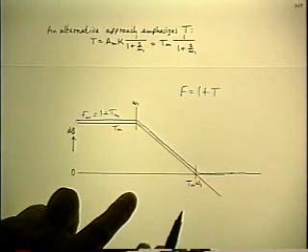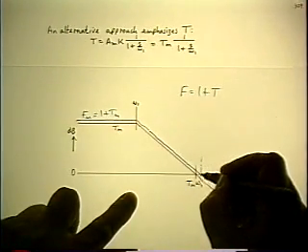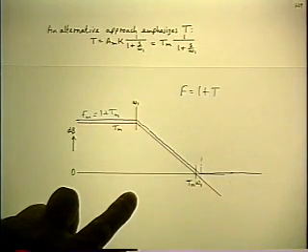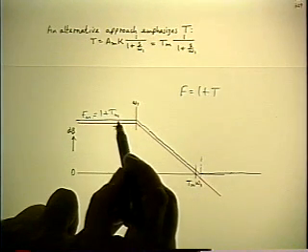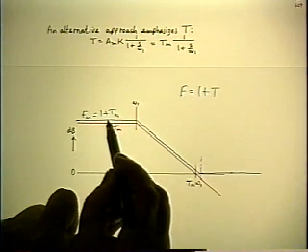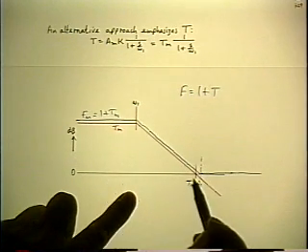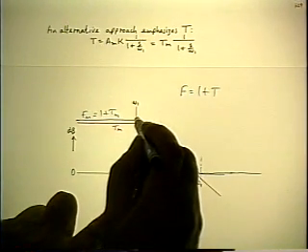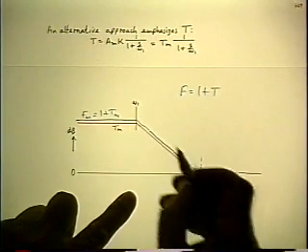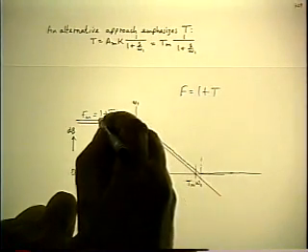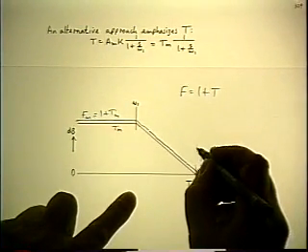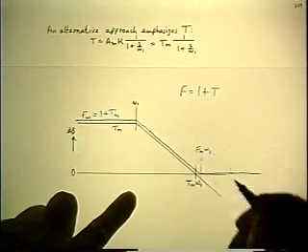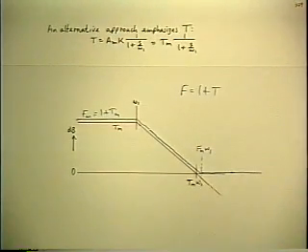If it's right, what is the value of this frequency? Well, gain bandwidth trade-off gives it to you right away. Because down here the magnitude is Fm. Down here the magnitude is 1. Here the corner frequency is omega 1. Therefore this corner frequency has the same ratio to omega 1 as this magnitude to 1. So the value of this corner frequency is Fm times omega 1. If that's correct. We're still out on the limb. We're still guessing.